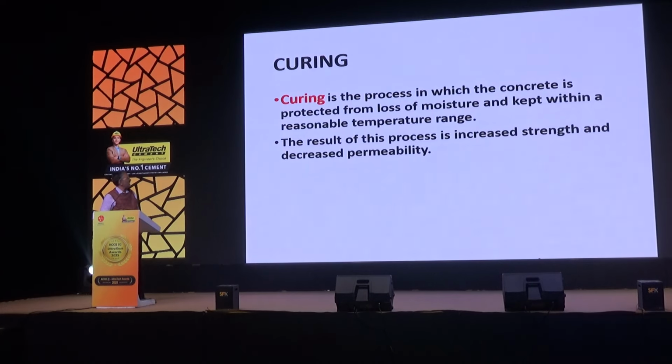And finally, curing. What is the curing period required for different elements? The curing period varies for various elements and the design mix also. And nowadays we have accelerated curing methods and also centering and decentering methods, the drop head system, the drop-in-position system. The concrete is not in isolation, so we decide about curing or decentering depending on the codal provisions. We have to design and engineer that.